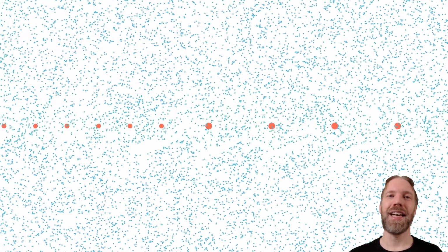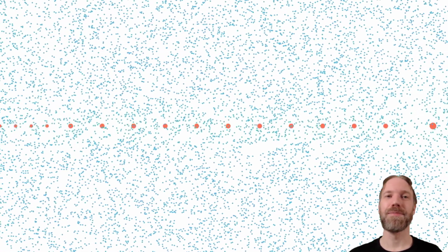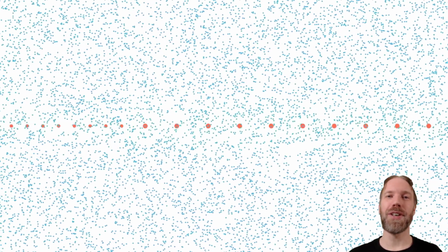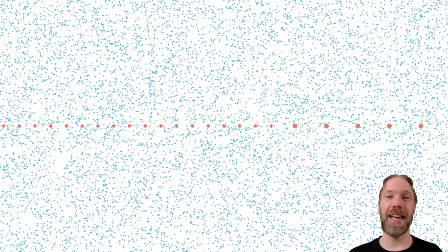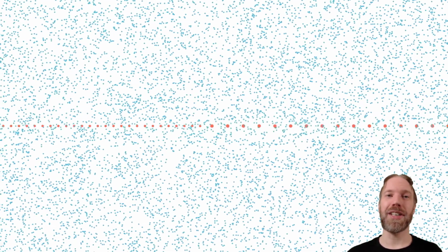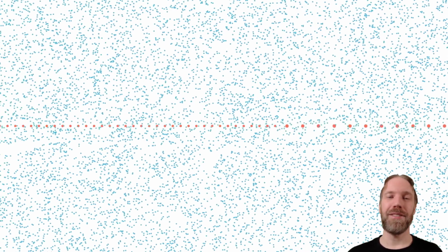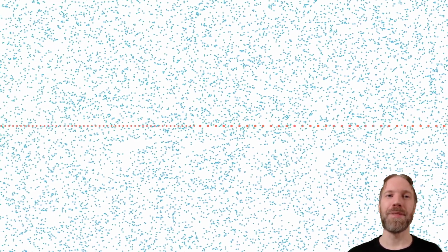In this illustration, I have made the vortices very small, which will give high velocities close to the center. The vortices are also moving on a fixed line, while in reality this configuration is unstable and would decay, which is one of the mechanisms behind the decay of the wake. Note that the closer the vortices are together, the more it looks like a jump in flow velocity. This illustrates the assumption of infinitely many, infinitely thin blades in the momentum theory. That is the case without additional losses.